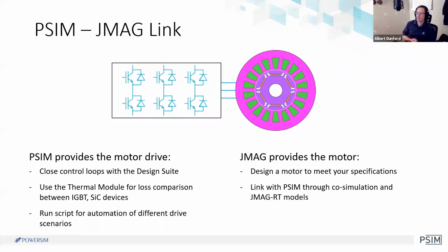models. Those thermal device models would provide us with switching loss calculation, and they would also provide us with thermal, heat sink modeling. So we could look at modeling a heat sink and then seeing what our junction temperature ends up at. We could also look at how those all interact there. We can switch to a non-ideal device model, and we can drive a more realistic switch waveform down the line.